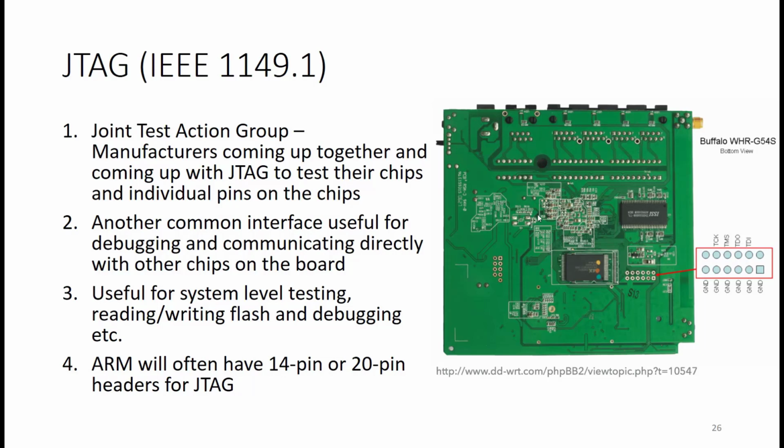In this case, you'll also find a clock signal pin in the JTAG connection, because you are sending the data from one component to more than one component through the same data line. As a standard by ARM, you might find a JTAG connector of 14 pin or 20 pin on the board of the device, but this is not always true for all cases, because for JTAG you can customize the pin and the sequence of pins.